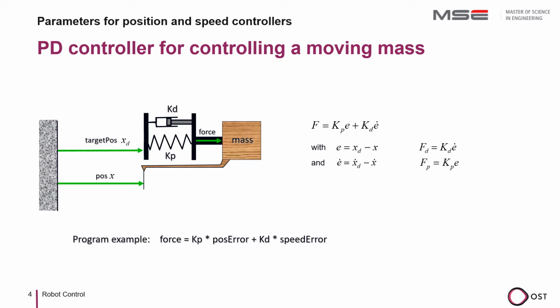At this point, you can see that when formulating the controller, the actuator and sensor values should be expressed in SI base units, because otherwise you cannot understand position error, velocity error, Kp and Kd values, and because you lose the relation to physical reality. In the swung out state of equilibrium, the system is at rest. The position error E and thus the spring force is zero.